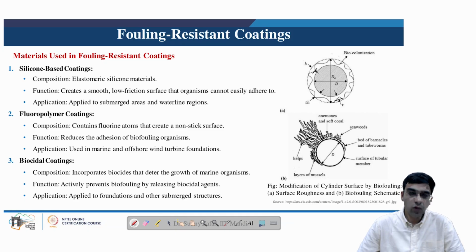Next are the fluoropolymer coatings. These coatings contain fluorine atoms that are helpful in creating a non-sticky surface. This reduces adhesion of biofouling organisms and they are used in marine and offshore wind turbine foundations.